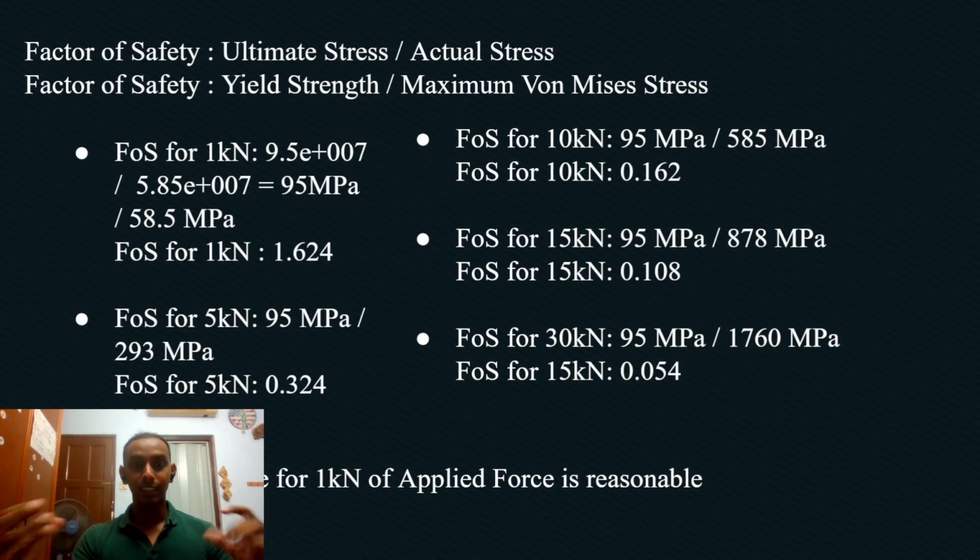So we know that, for example, this valve has to withstand all that heat during combustion. So it has to be designed in a way for it to dissipate and handle the heat that is being produced while also maintaining peak performance and peak function. This analysis, which is the thermal analysis, static analysis, and moment analysis, was done for the connecting rod, and an example of moment was done on the camshaft because we understand that the camshaft is constantly rotating.